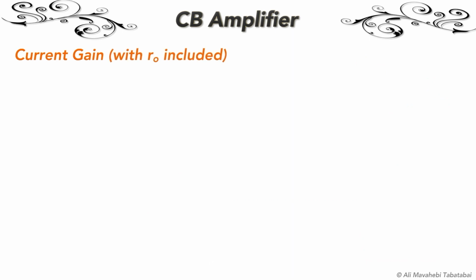We can use the voltage gain to calculate current gain of an amplifier. The current gain is the ratio of the output current over the source current. The output current is the output voltage over the load resistor, and the source current is the source voltage over the input and source resistances.